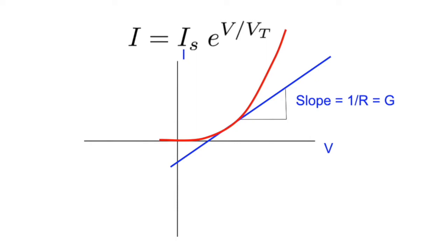And so we can look at that curve, that red curve, and say, okay, what does that tell us? It tells us that it's not a linear function, or at least not linear throughout. Remember, we looked at functions before, and we said this is piecewise linear. Here, the bottom is piecewise one part, and then further along as you go to the right with voltage, there's another part that is piecewise linear, and in between is this exponential transition.